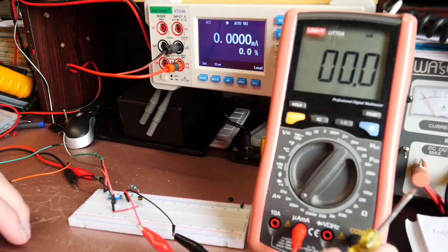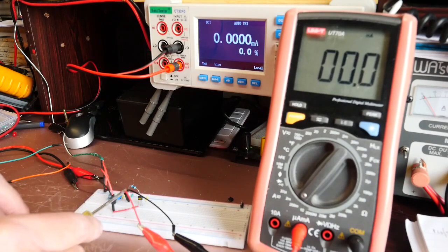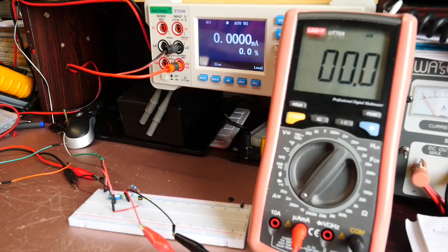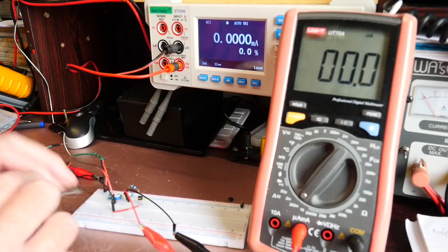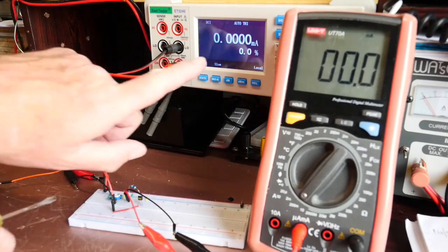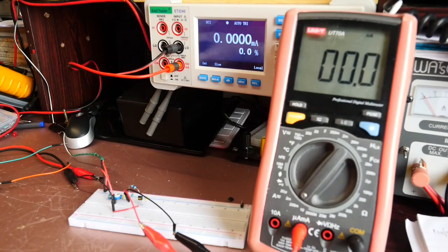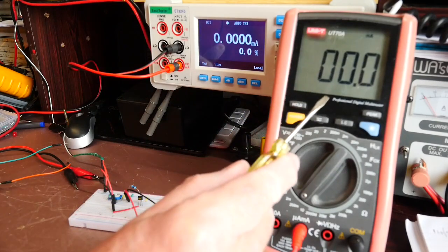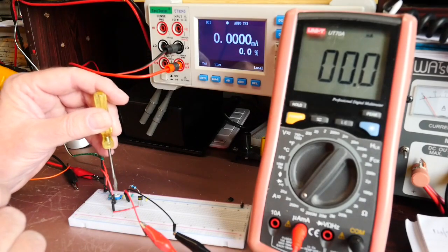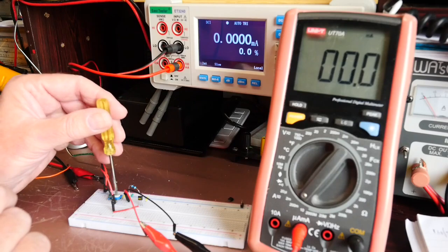This meter is measuring the collector current, so the current from the collector to the positive rail through that 1K resistor. The base of the transistor is connected via this potentiometer here to allow me to control the base current, and this meter is measuring the base current, and currently, as you can see, it's 0. In fact, they're both 0, so the transistor is most definitely not conducting. So just to make you aware, that is milliamps and that is also milliamps, and that'll become significant in a moment. So I'm now going to increase the base current